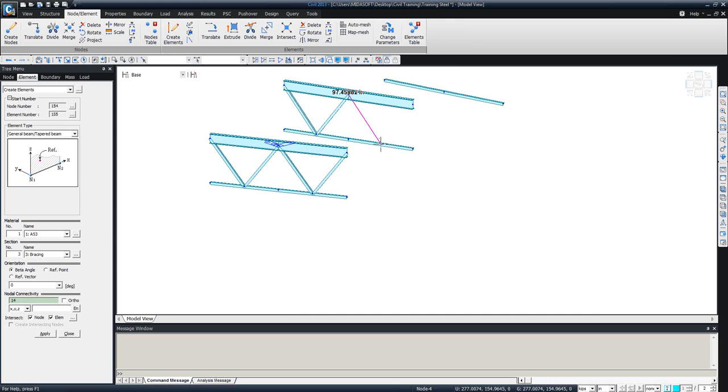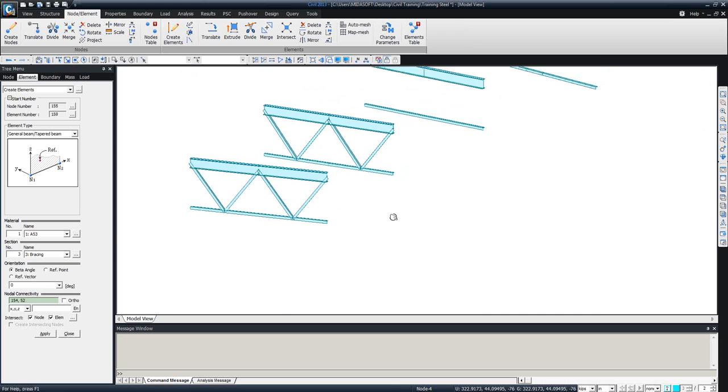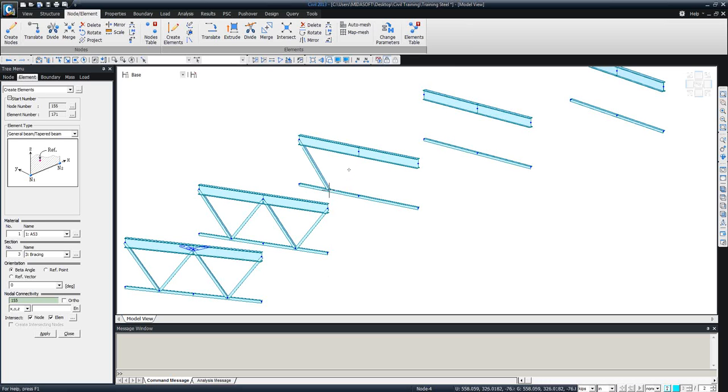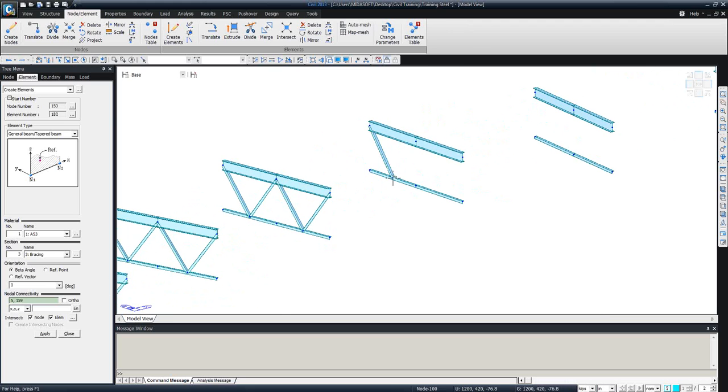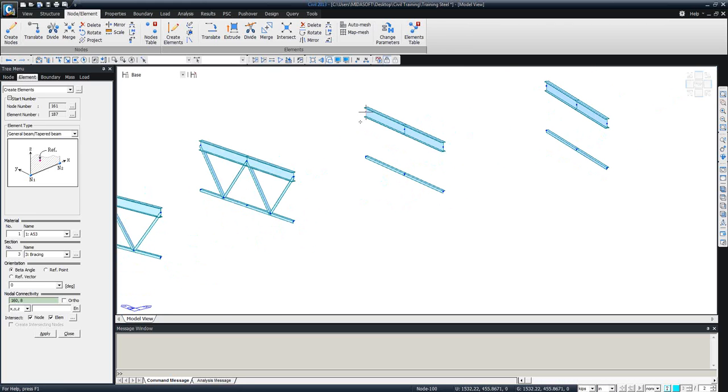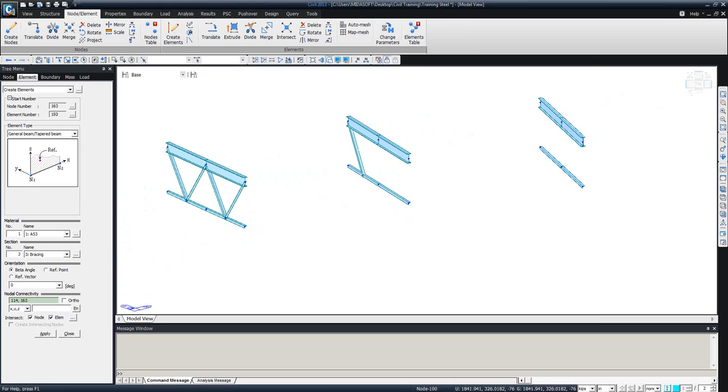Just know that what we did is we actually created these additional nodes down here and down here and down here, but these are not connected to the top of the girder because we are supposed to make the girder and these cross frames work all together as one system. So to fix that, to ensure that they are connected as they are supposed to be, we're going to use the elastic links of the rigid type to make that connection. That's a very simple step.